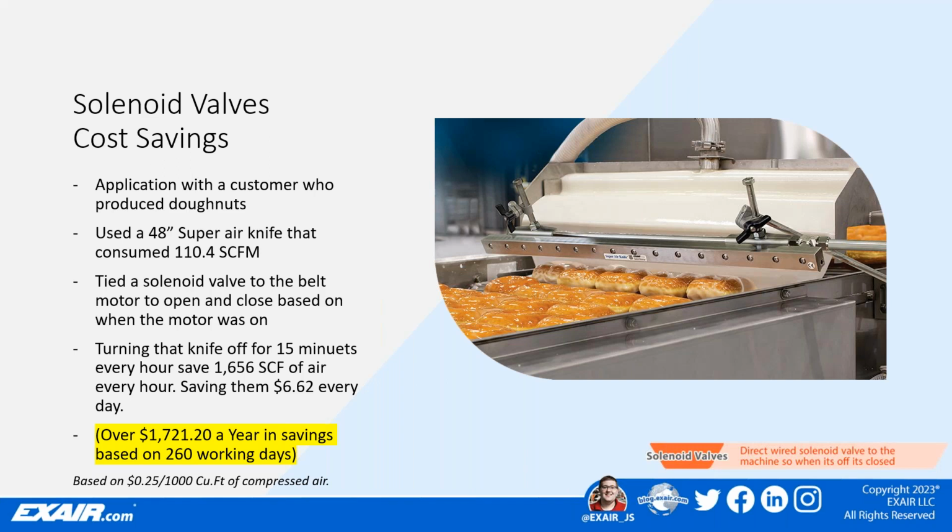The knife worked great. That knife consumed 110.4 SCFM at the running pressure of 60 PSI, which is what they had it set to. Due to the process and the frequent changeovers, there would be long stretches of time when the glaze line wasn't moving. So they installed a solenoid valve tied to the motor that moved that belt. When the motor got power to turn on, so did the solenoid valve, and it opened. So when the system stopped the belt for any reason, the air knife would also turn off. And when it started back up, the air knife would be turned back on.